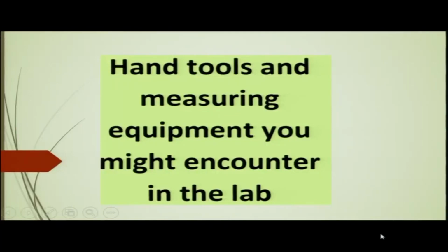You can also see this in many pulling doors, for example: if you pull the door from the top, at any level it can stay, and it will not go back if you leave it. So, these are the worm and worm gear, also used of course where you need very high torque to be transmitted. These are basically the transmissions that I wanted to tell you, and through these mechanisms, mostly in mechanical engineering, the power is transmitted from the input shaft to the output shaft.